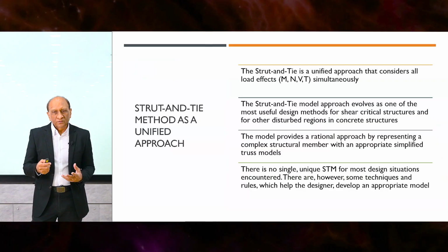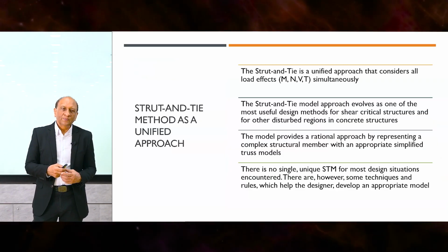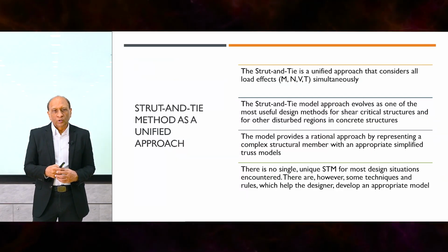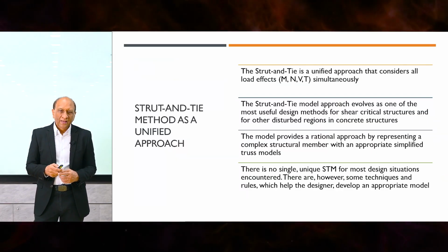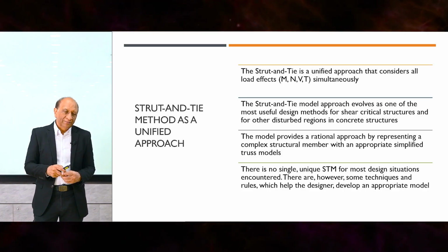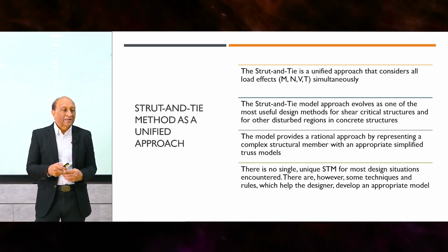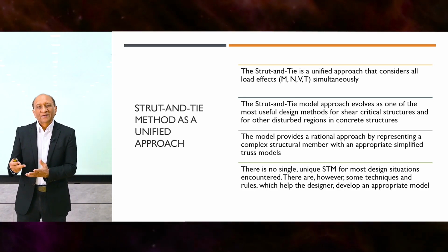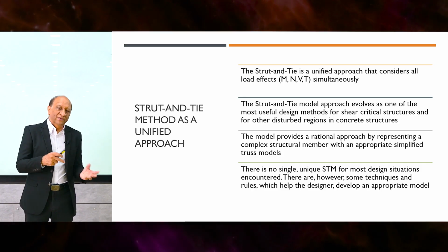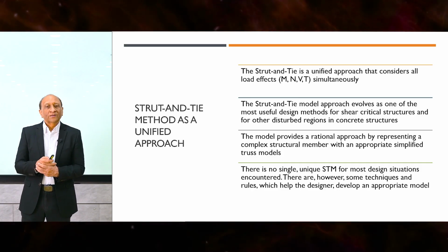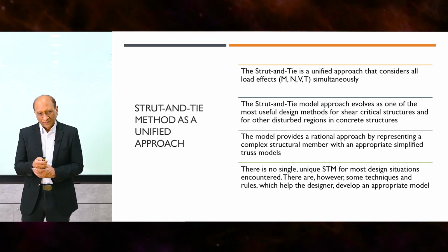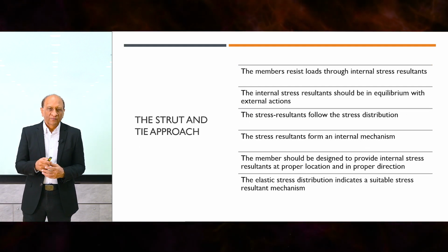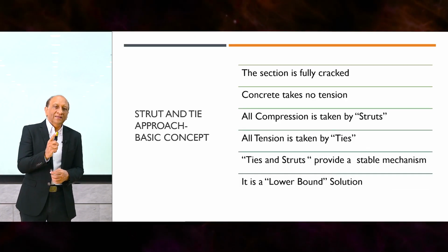It has evolved, and it's evolving to especially apply for structures with predominant D regions. There is no single unique STM. That's the beauty of this. You can create multiple models, and most efficient will be the one that we should be using. Some will be valid, some invalid, but multiple ways load can be transferred that you can conceive. And then this is just the basic principle that I have already mentioned. I don't need to repeat that. The main thing is here.